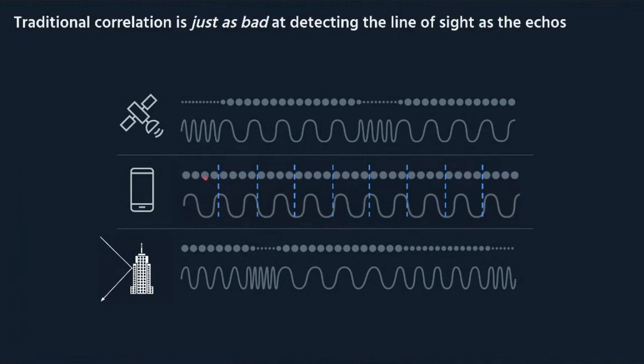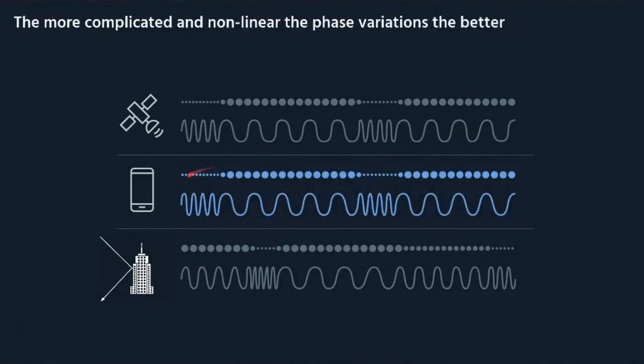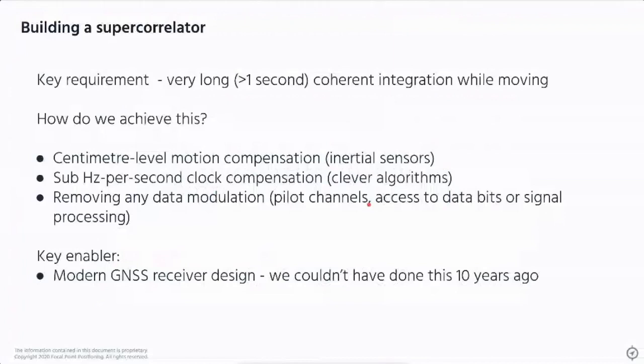So normal GPS processing uses very small sequences of exactly the textbook data to keep trying to pick up radio data. A key difference between supercorrelators and old correlators is that we use a very long sequence and we tailor these phase patterns correctly. It sounds easy. In practice, it's very hard, which is probably one of the reasons why it's never been done before.